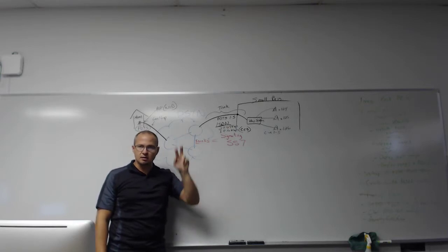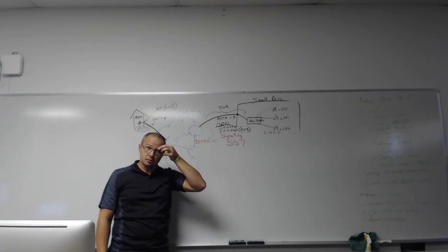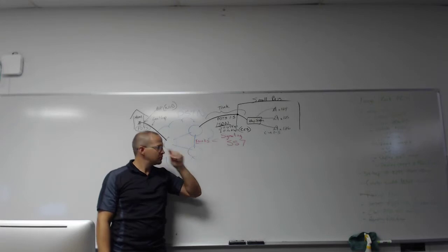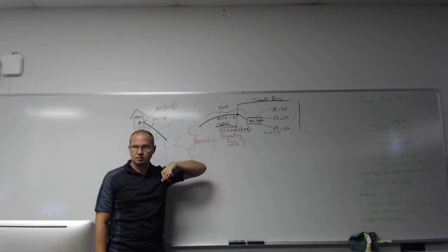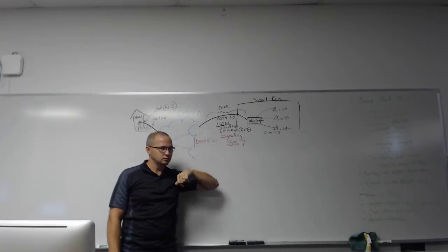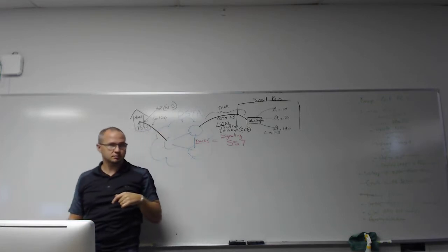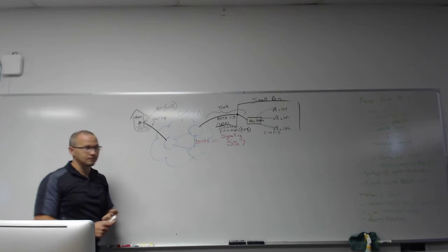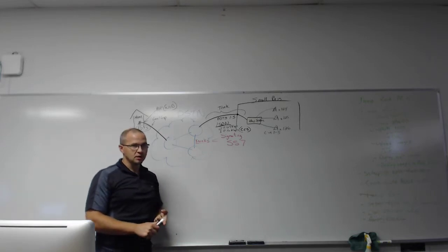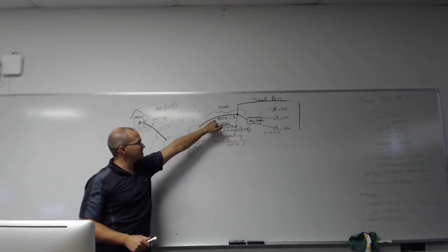So ISDN still comes in on 2 wires, but it's split up into 3 channels. Does that make sense? So it's still broadband communication, channelizing the signal that's coming in, and it's digital. It's a digital signal where a POTS line is analog.